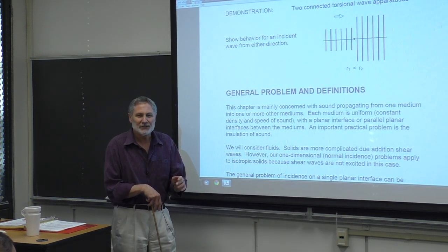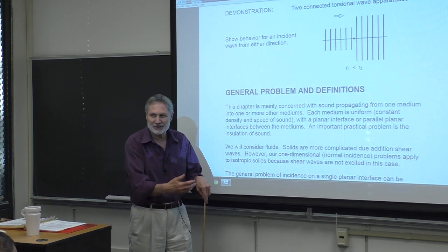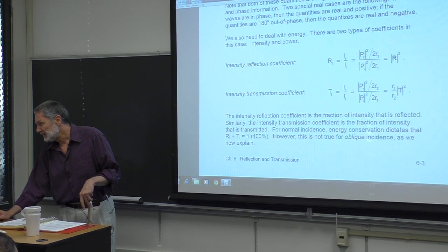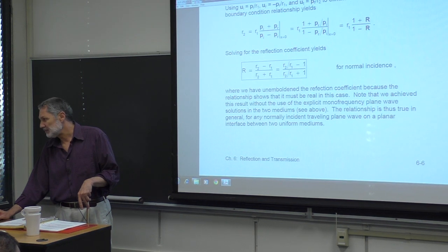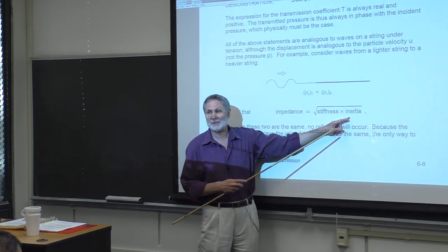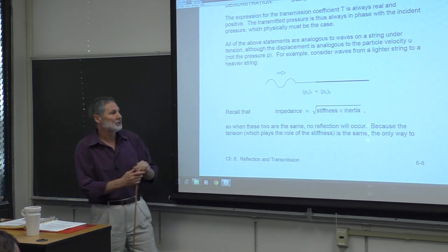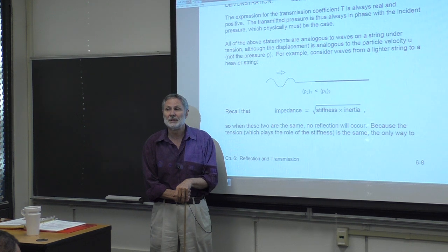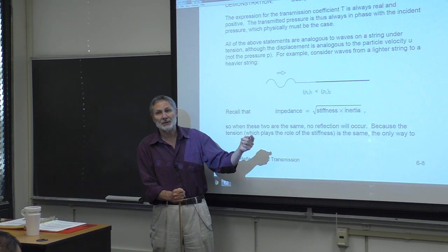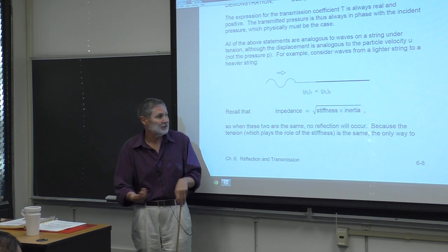Now, it's a little counterintuitive, and the reason is we're all thinking the same thing, including me. We just naturally think speed of sound here. It's not the speed of sound that we're dealing with here, right? That's coming up eventually. That goes like the inertia divided by the stiffness. This is a different quantity, the impedance here. So it turns out that because of that greater inertia, to match the impedance, you want less stiffness, so you'd have a smaller diameter. Alternatively, you could make the diameter on the left side greater to balance that less inertia there, either way.